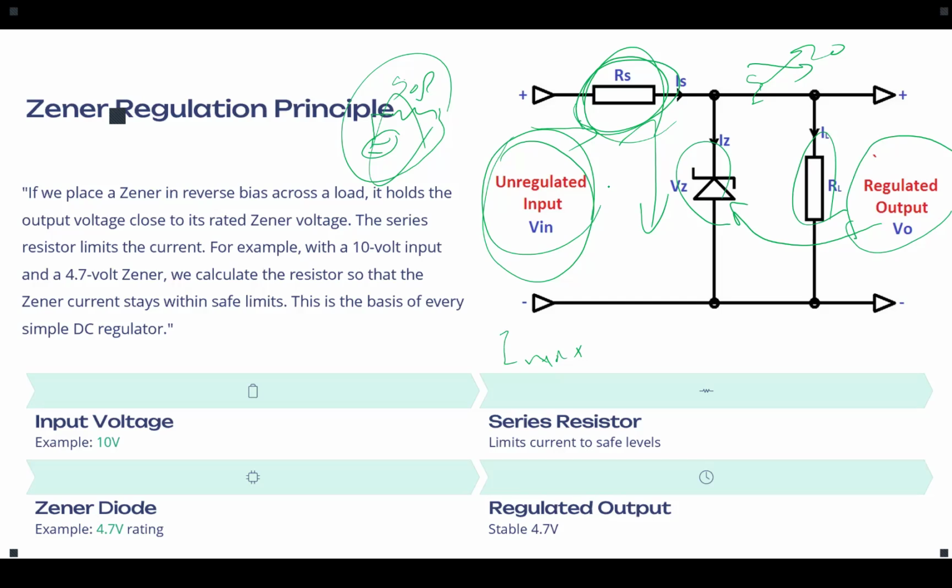The rule of thumb is a safety factor of 10. If you calculate your safe resistor and come to 1 kilo-ohm to meet the I max criteria, you need to apply the scaling factor, the rule of thumb is 10, and put a 10K resistor in your circuit. Now we are conservative enough that we never pass that I max. Remember, the current should not get lower than I need. So this is a trade-off.